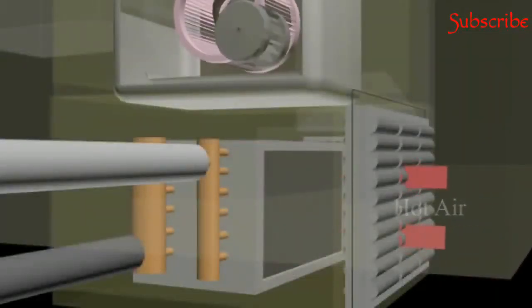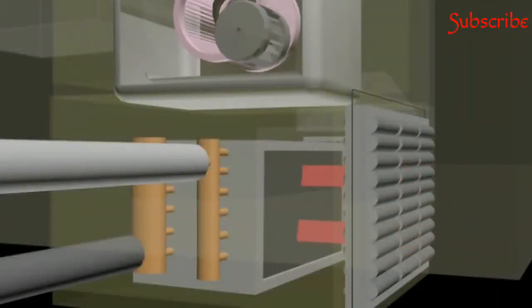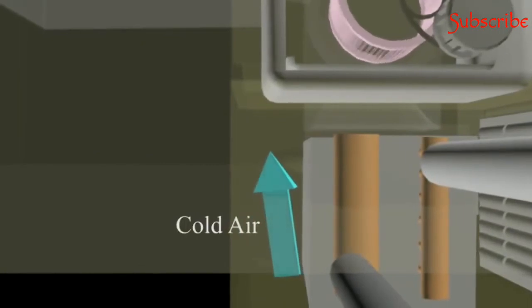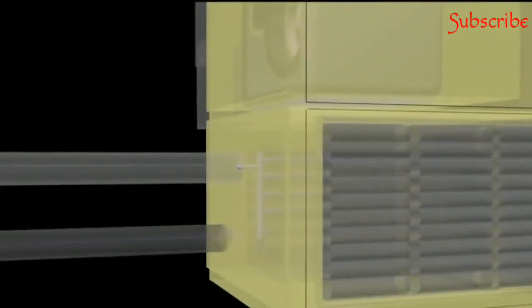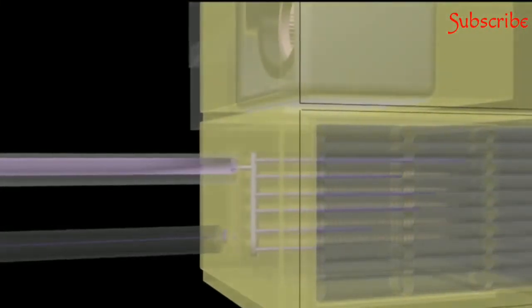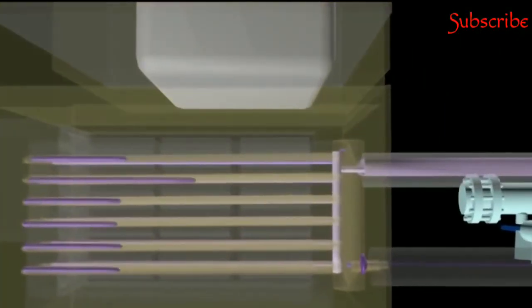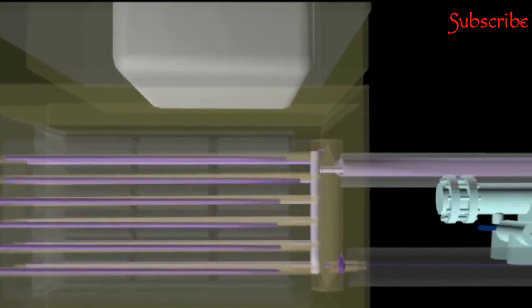In the cooling coil, the hot air will go through the cooling coil and switch to cold air due to the heat transferred to chilled water. Cooling coils commonly used in this system are tube and fin. After absorbing heat from the hot air, the chilled water will be known as chilled water return. Normally the chilled water return pipe will be colored light blue.